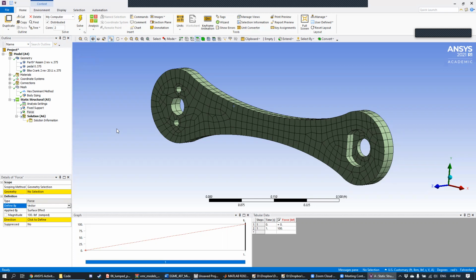Because when you're doing these simulations, you want to think about what's the situation, or how are these things going to actually be applied in practice. And so for this particular activity, I want you to look at the worst case scenario. What loading condition will result in the most stresses along the bike crank? But actually, the beautiful thing about finite elements is you can actually try both.